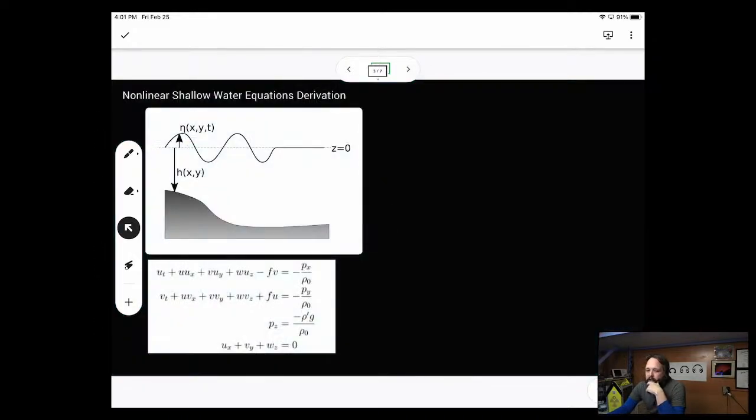So where we're going to start today is on a little bit of a derivation of the shallow water equations, and we'll cast everything in terms of a conservation law, take a look at the discretization, and talk about how we're going to actually implement this in SELF. And in the latter half of today, we'll get into the code, do some implementation, and start doing some test runs. So the shallow water equations, they are in some sense a subset of Navier-Stokes.